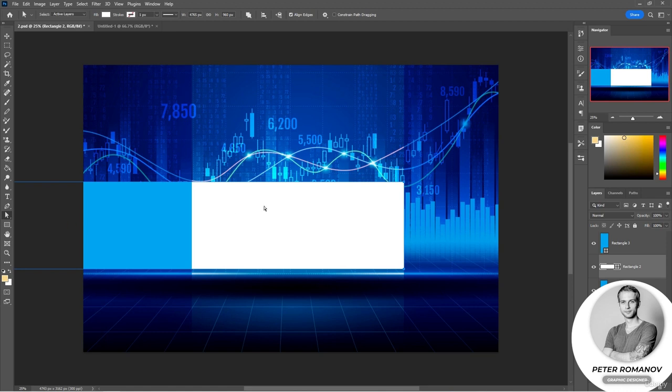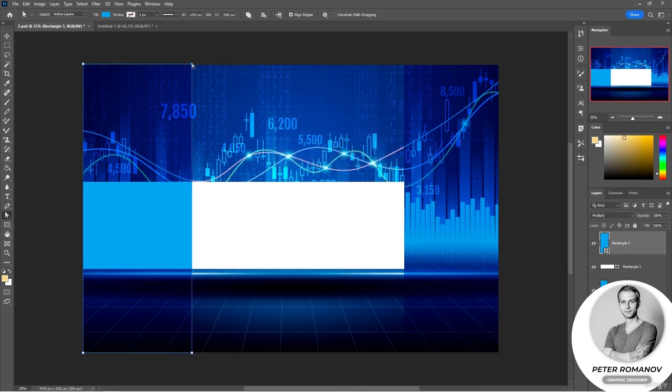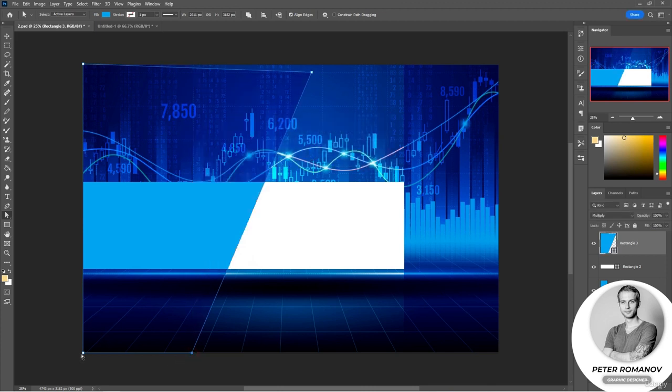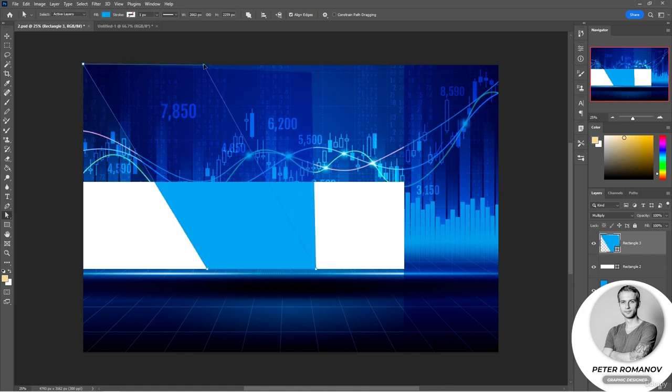Take the white arrow and look, I'm going to switch to this rectangle. If I click on the corner, then I have these 4 anchor points at the corners of our rectangle, and I can already do something with them. For example, I can pull this point and somehow move it. I will get something like this, for example. I can select 2 points at once by holding down the Shift key, and in this case I can pull on this bottom side and make, for example, a parallelogram from our rectangle. That is, with this tool you can click on any anchor point, which is usually located somewhere on the corners, and change the location of this particular point.